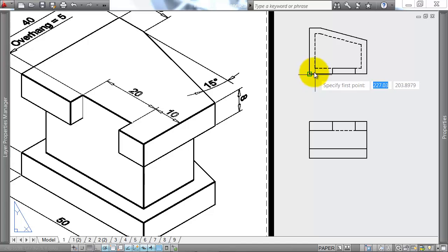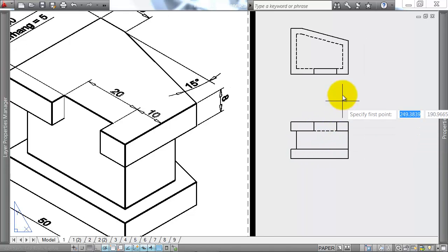Now, what else do we have? In line with these hidden lines in here are talking about the middle part of the shape. So if I want to locate the middle, I can use those hidden lines, like so. And starting to locate that side, I can locate this side in the same way. And erasing the construction lines I used there. So this view is now almost complete.